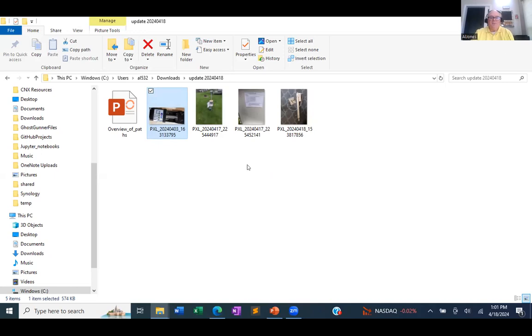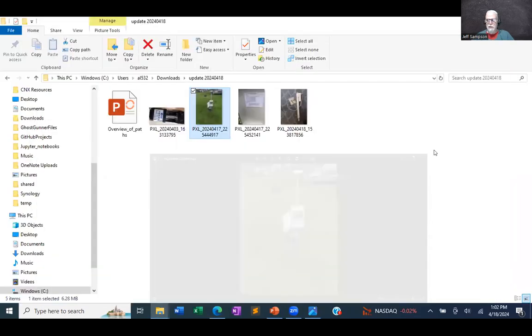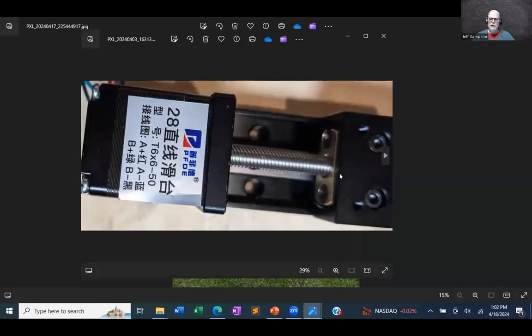What I have spent time on as far as power on that motor, I noticed it was some kind of a micro stepping driver that you have. You can play with the number of steps. It could be if you say just do one step per command as opposed to doing a bunch of little steps, you could get more torque one way or the other. So that's something else you could play with.